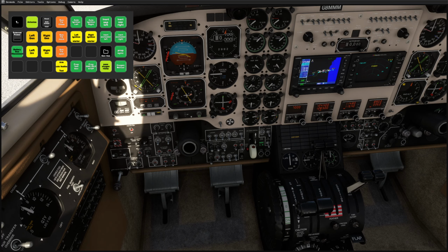The next one is the propeller governor test, which is here. And it says hold it to the governor check. So I'm going to hold that button in. And individually, I need to advance each one up to full power, and I should see the propeller limited to 1600. There it is, that's fine.